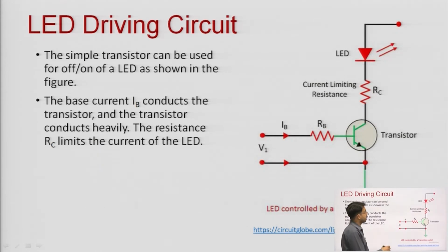So, we always have to use a current limiting resistance with the LED. So, what can we do? We can simply make this circuit, use a resistance,